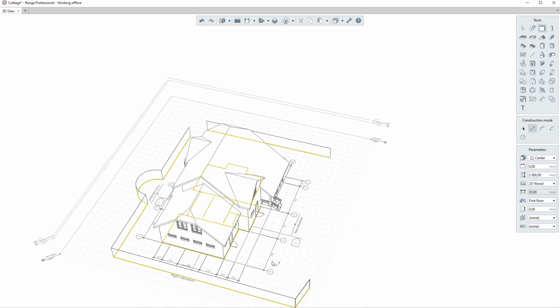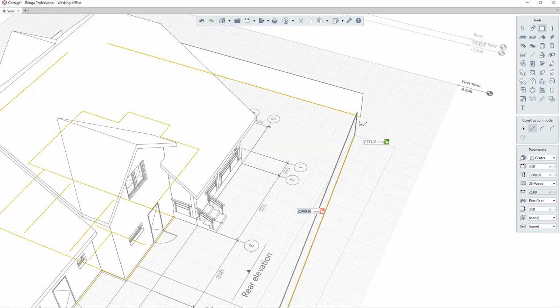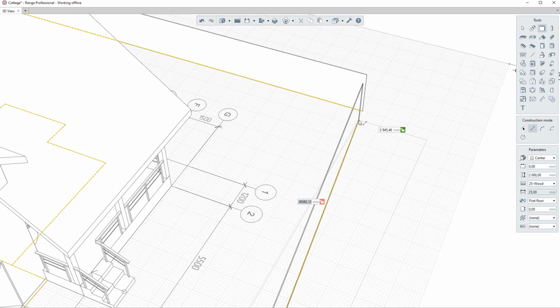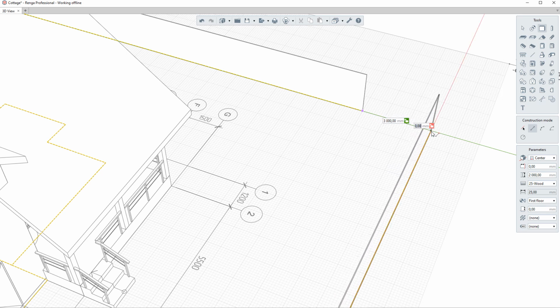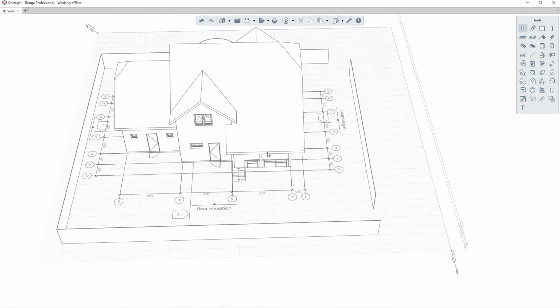It is necessary to finish a new wall at the end of the first wall. For that, call a tracking snap. Keep the mouse cursor at the end of the first wall. When the point changes color, use the mouse cursor to set the tracking direction to the expected point. Click the left mouse button. Press the Escape key twice to complete the command.